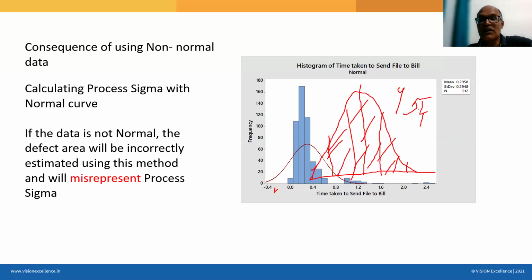Ultimately we want to achieve our points in 6 sigma, right? So what should it be? 99.9997%. We typically call it 3.4 ppm, right? Yes, that is 3.4. That means if you get a fantastic 6 sigma process, and you produce 10 lakh parts, only 3.4 parts will go outside the specification limit. That is what we typically call a 6 sigma process.